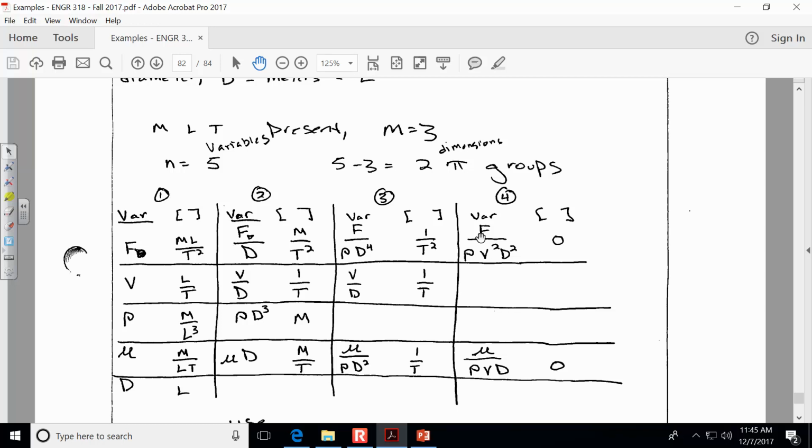So look at what I did there. Diameter has units of length. Length is in the numerator of the force variable group. And so if I have force divided by diameter, that cancels out the length parameter from the resulting combination. With each step, I'm trying to simplify the units so that eventually the group is unitless. And so I've accomplished that.